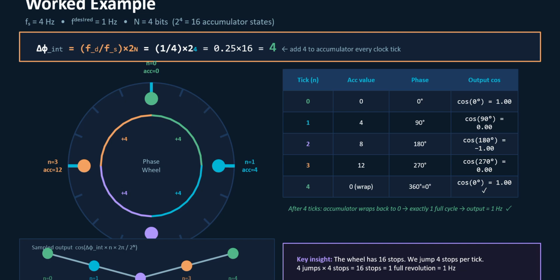Inside the DDS, from the number it gets, for the case of number 1, it gets pi over 2, so that's 0. For the case of 2, it gets pi, that's -1. In the case of 3, it gets 3 pi over 2, that's again 0. And in the case of 2 pi, it gets the number 1.